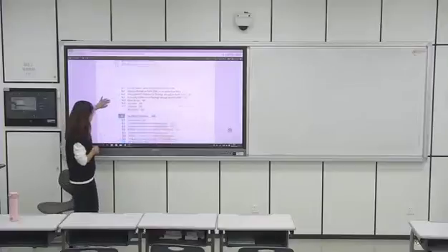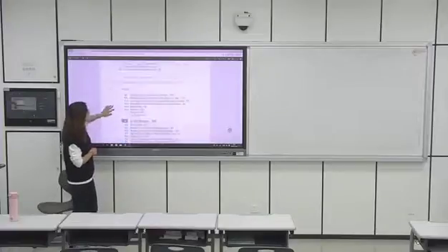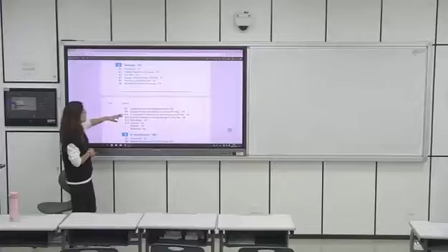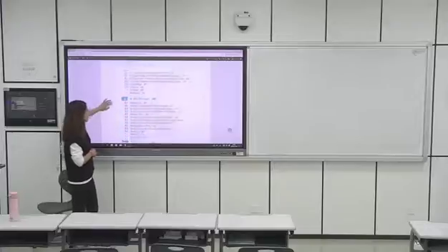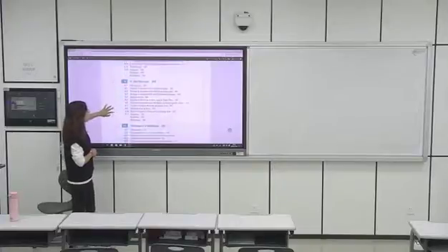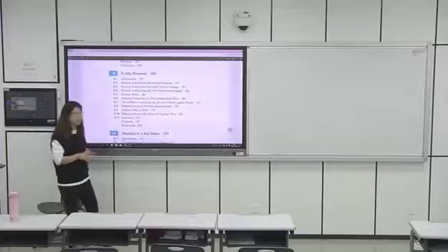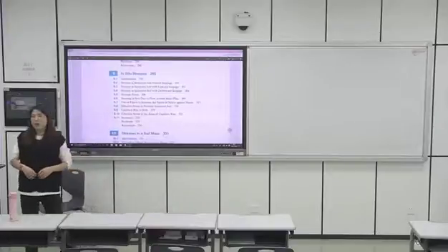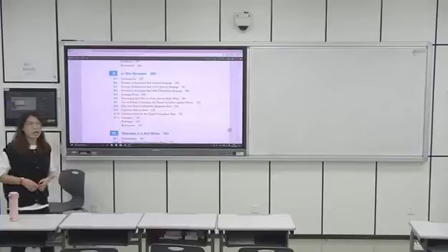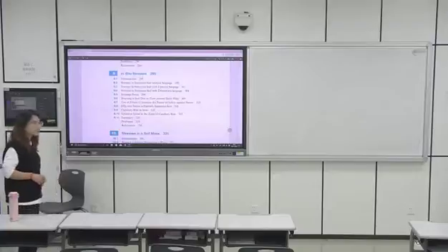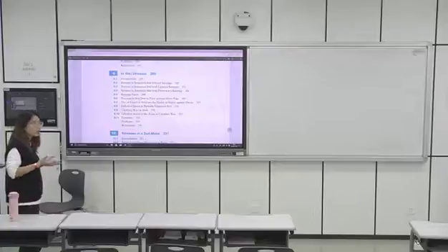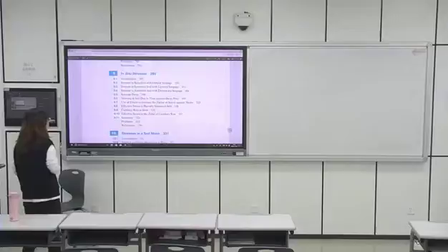We first jumped to in situ stress and then went back to learn the flow net and uplift pressure, right? Let's see, in situ stress. We said that we learn in situ stress because if you want to calculate settlement or shear stress of a soil, first you need to know what the overburden stress is, right? How much the overburden stress is.